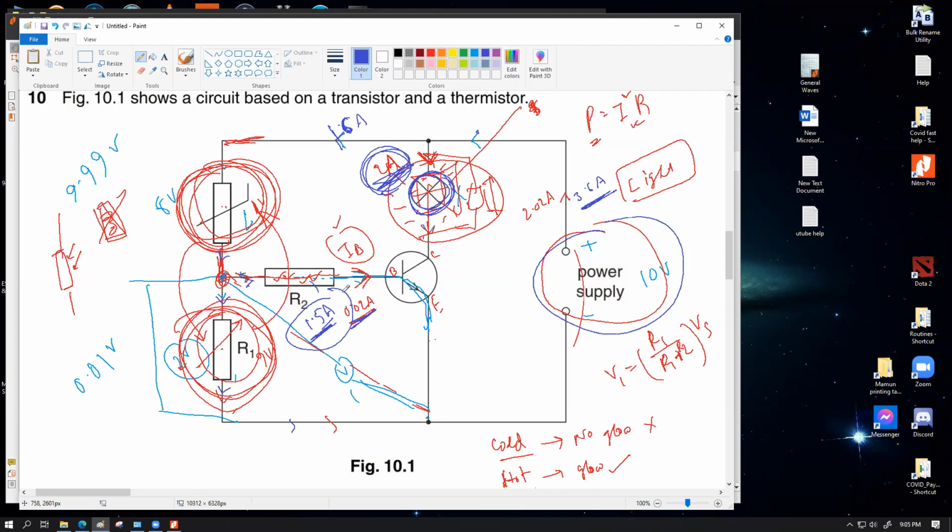And another important reason is that a transistor is an electronic component, and we have made this component work by altering the property of the semiconductor piece at the atomic level. They have a certain maximum current handling capability, like I showed you in the last class that a 5 ohm resistor can be of different sizes depending upon the power rating. Transistors are typically not designed to handle that kind of large amount of current. They are designed to operate at a very small amount of current for most part.